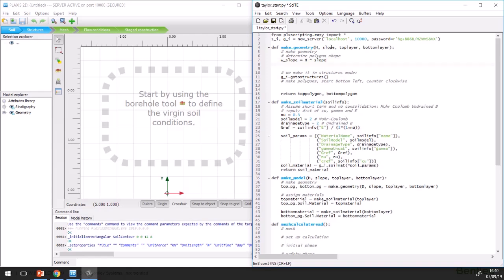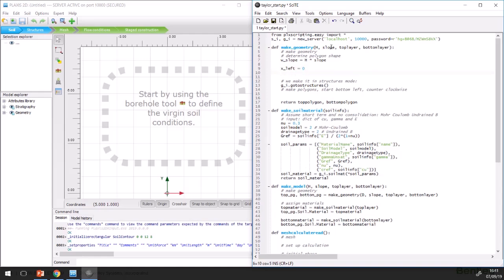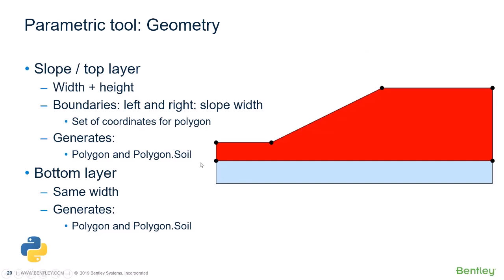Now if you look at the horizontal coordinates, the X coordinate, I will make our left boundary, in this case, 0. If I circle back to our PowerPoint presentation, I'll start here. This is the first X coordinate, then I want to move to the toe of the slope, then to the crest of the slope, and then define the right hand side boundary.